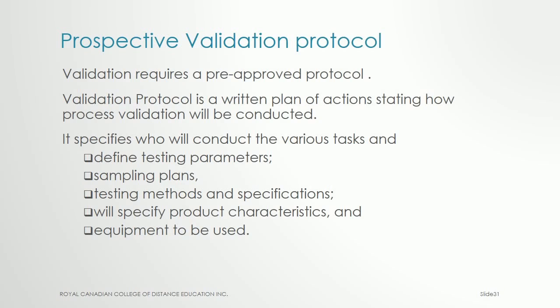Validation requires a pre-approved protocol. Validation protocol is a written plan of action stating how process validation will be conducted. It specifies who will conduct the various tasks and defines testing parameters, sampling plans, testing methods and specifications. It will specify product characteristics and equipment to be used.